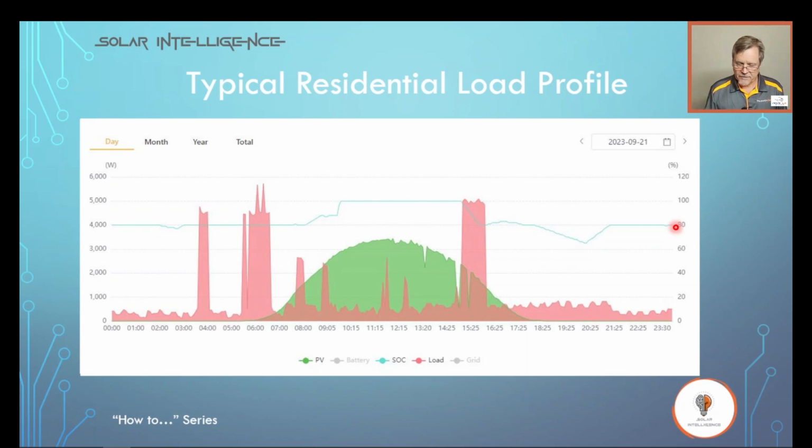When Eskom fails, then only will the battery drop below 80%, and when Eskom comes back on again, well then the grid will recharge your battery back to that preset state of charge level. All right, but the grid will never charge the battery higher than that percentage. Obviously you want the sun to do that.